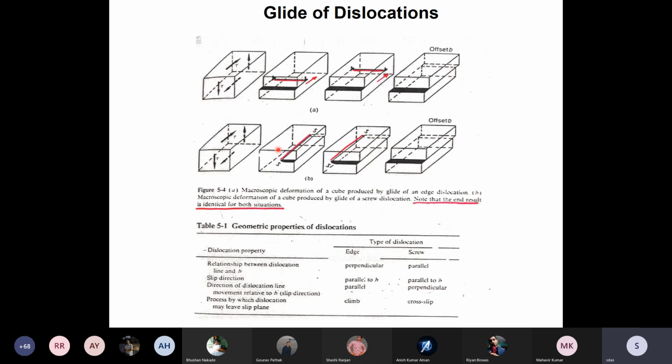The cable is made of 99.95% pure copper or higher purity. Any impurity atom in the copper is a center for scattering of the free flow of electrons. It increases resistivity. Grain boundaries and dislocation lines are also scattering centers for the free flow of electrons.